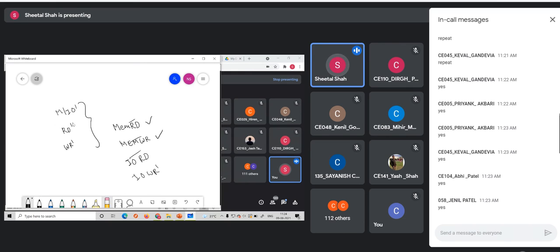So for this, I can use a 3x8 decoder. To this, I can have 3 input pins: M/IO bar, read bar as well as write bar. If it is 000, then it should be memory read bar. If it is 001, then it can be memory write bar, and so on.